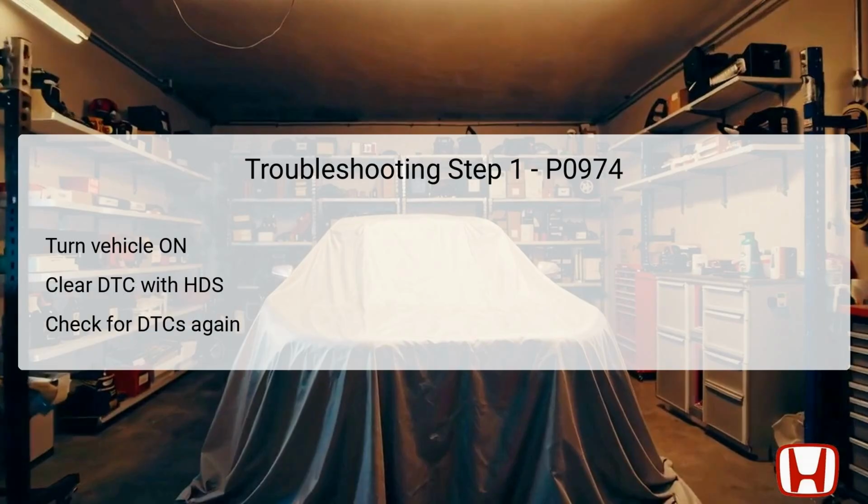electrical connections. For the second step, ensure to turn the vehicle to the off or lock mode before proceeding. Check fuse number C31, which is a 7.5 amp fuse located in the under-dash fuse relay box. If the fuse is intact, it indicates that the circuit isn't affected by a blown fuse, allowing you to move on to the next step.